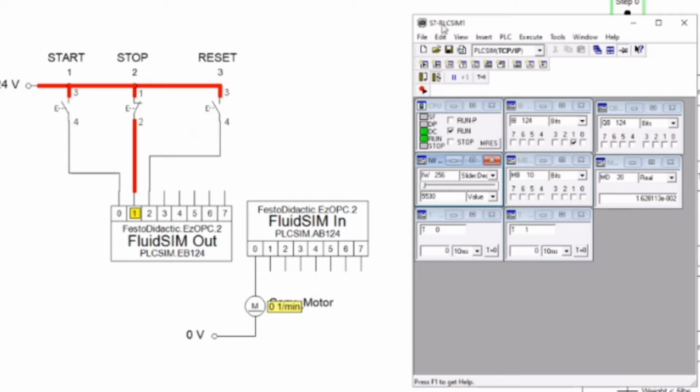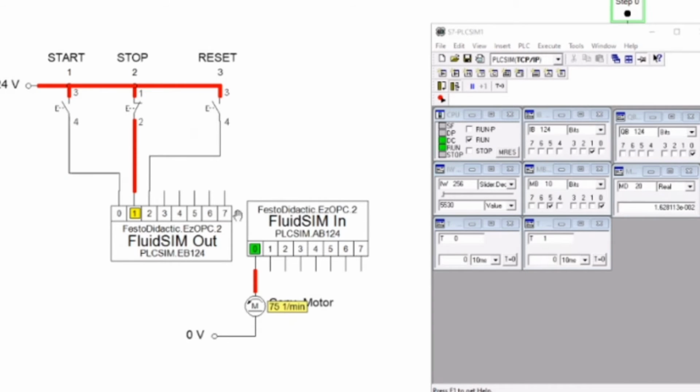So starting our program, it turns on the conveyor motor and it registers both the step memory and the run memory. And so when the conveyor motor is constantly running, we assume that now a pallet has reached the weight scale, and here we can put a certain weight. So for example, a value of 10,000 is more than enough to register a weight more than 5 pounds. So by putting the 5 pounds, the timer of 4 seconds starts to stabilize the weight, and a new memory has activated, which is memory 6.